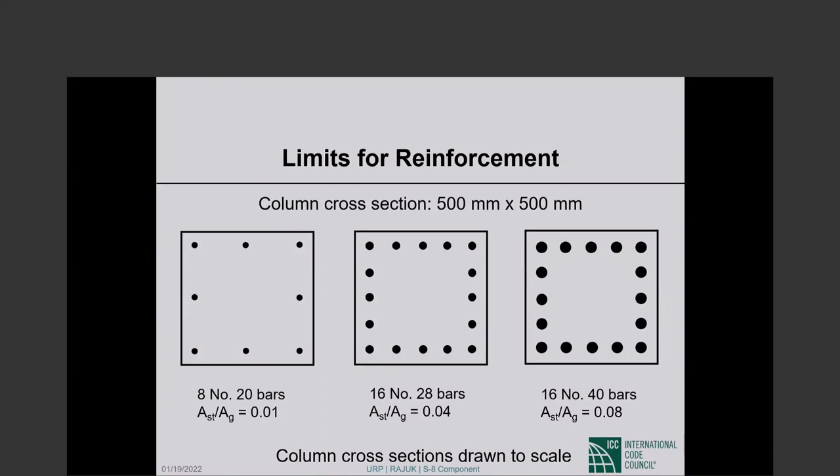Okay, now remember very importantly, we haven't discussed this yet. I hope to do it in non-seismic detailing. These column bars have to be tied and cross-tied. Okay? There will be one tie all around, and then every other bar, this one and that one, has to be laterally supported by a corner of a tie or a cross tie.